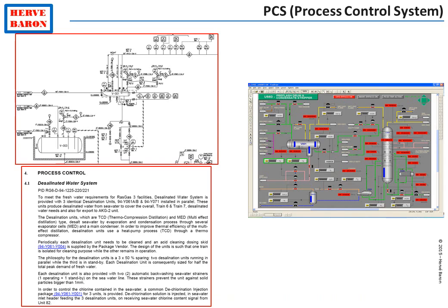They are defined by means of two documents. First of all, the P&IDs, which show the process controllers, as well as all the instruments that are part of the process control system, as well as control narrative or functional analysis, which are issued to explain in more details the control functions that shall be implemented in the process control system. The application software of the process control system is developed based on these two documents.